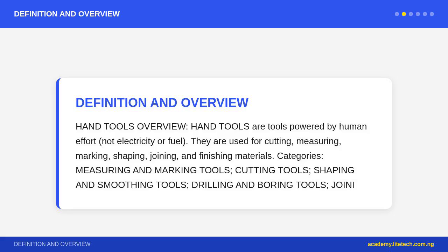Cutting tools. Handsaw, a long blade with teeth for cutting wood. Types: ripping saw, cuts along the grain, fewer, larger teeth; crosscut saw, cuts across the grain, more, smaller teeth; tenon saw, shorter, finer teeth, rigid back, for precise joinery cuts, mortise and tenon joints.